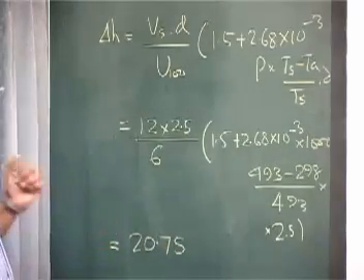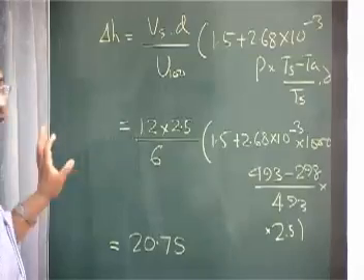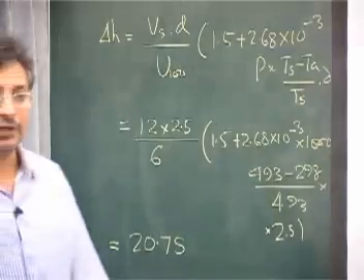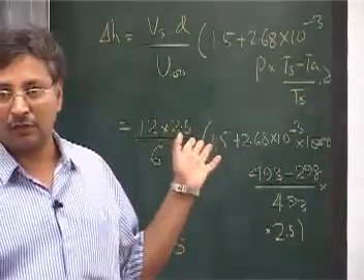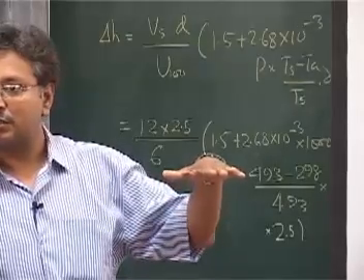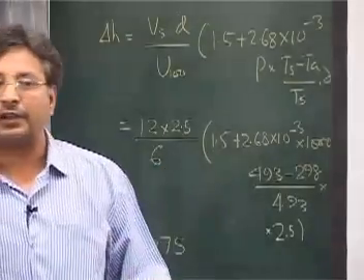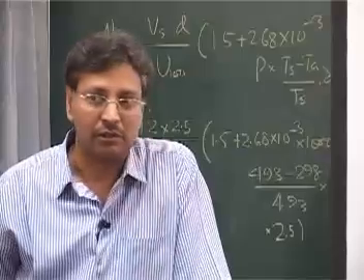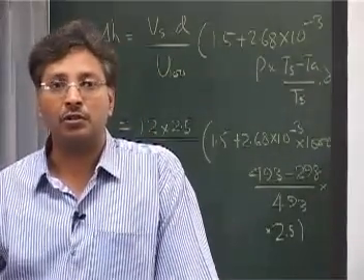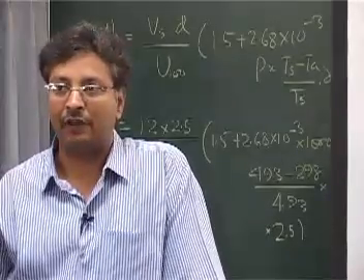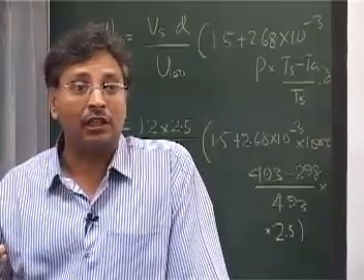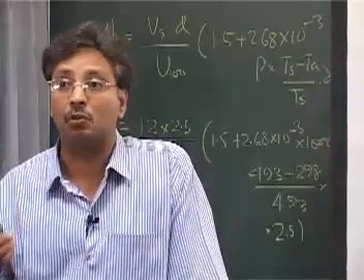20.75. Okay. All right. No question of aerodynamic downwash in this case. You remember the aerodynamic downwash we talked about? When the stack speed is high, 12, and the horizontal wind is 6, do you expect any aerodynamic downwash? We don't expect, because the ratio of Vs to U is much more than 1.5. Otherwise, if that was the case, we would correct the height for aerodynamic downwash.